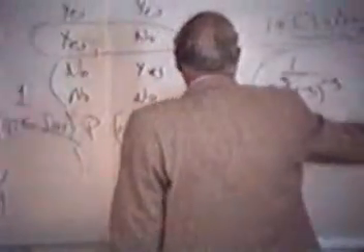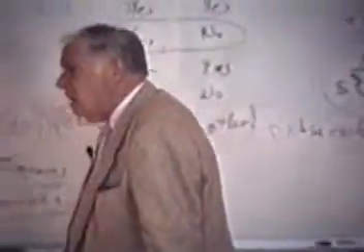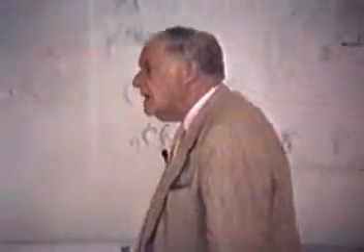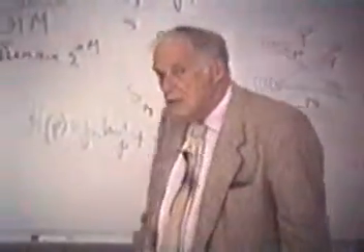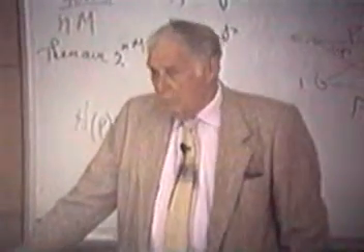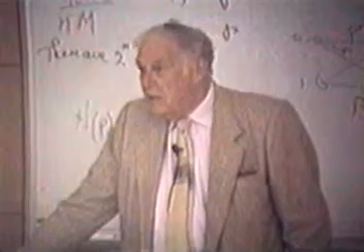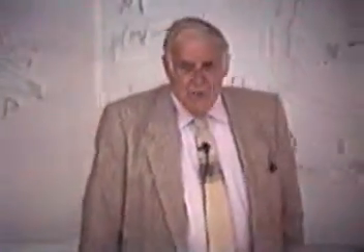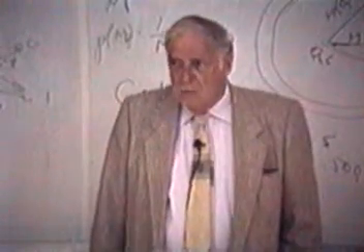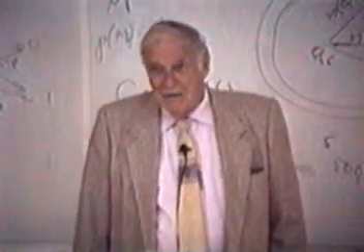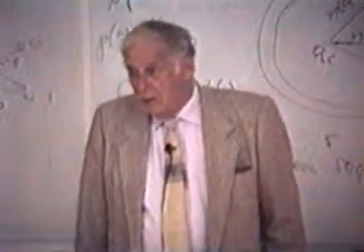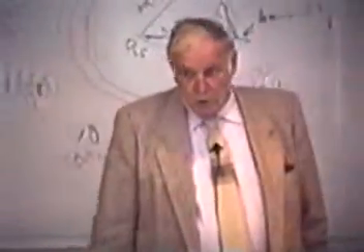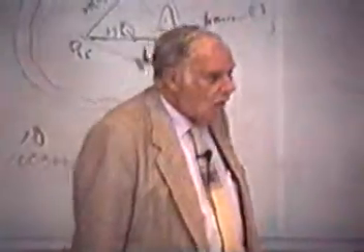And these likewise. Those are calculating methods. They are not random codes. They are very carefully calculated ones, correcting up to 100 errors or more in a single block. It can be done. This is what you have to do in a jamming situation. When the opposition is trying to jam you, he's got more power locally than you've got, and he's only got to knock out a few bits here and there and you're in trouble. So you have a very great problem.